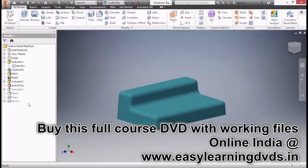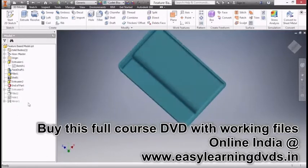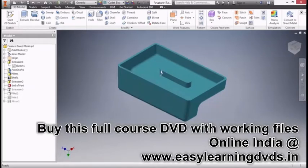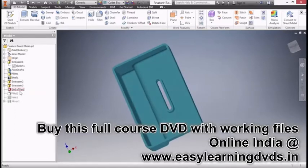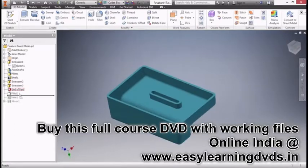Next, we'll go below to extrusion 2. Again, you can't see anything happen because it's actually on the underside. Here, a protrusion was added to this. And then we'll go down to extrusion 3. You can see a hole was added to this, a slotted hole. And then another fillet to smooth those edges there.